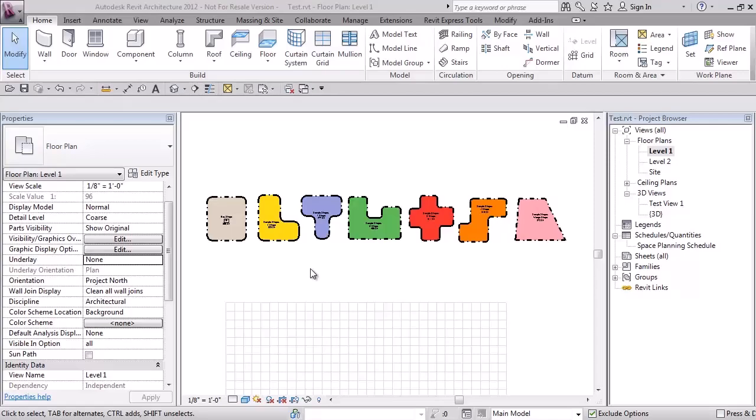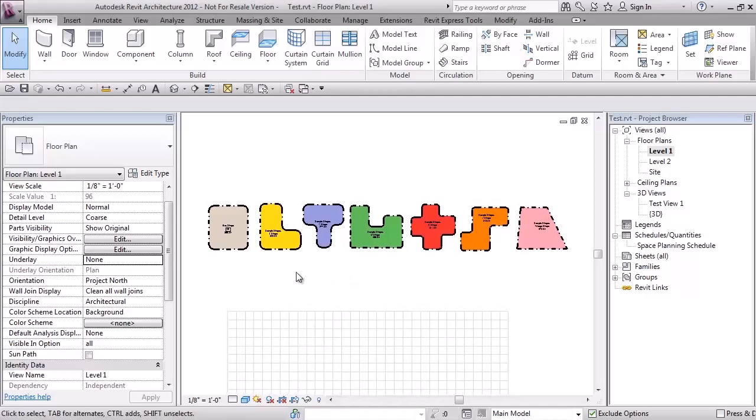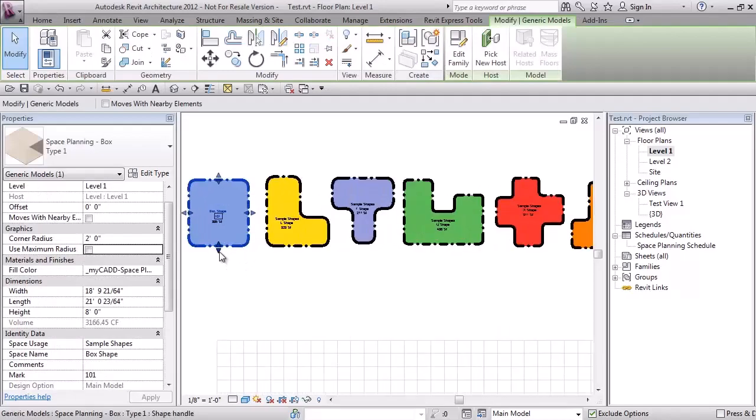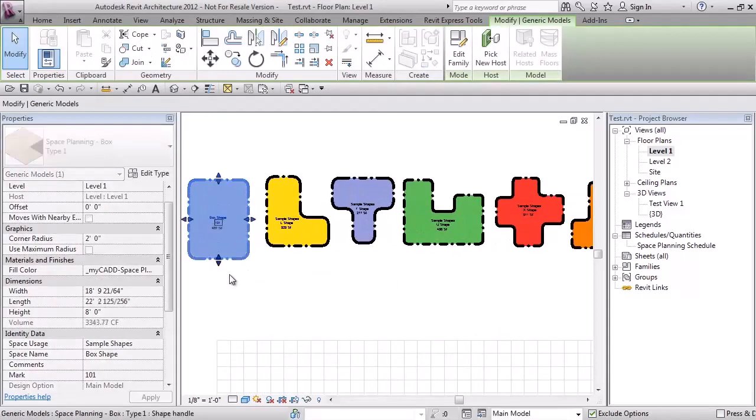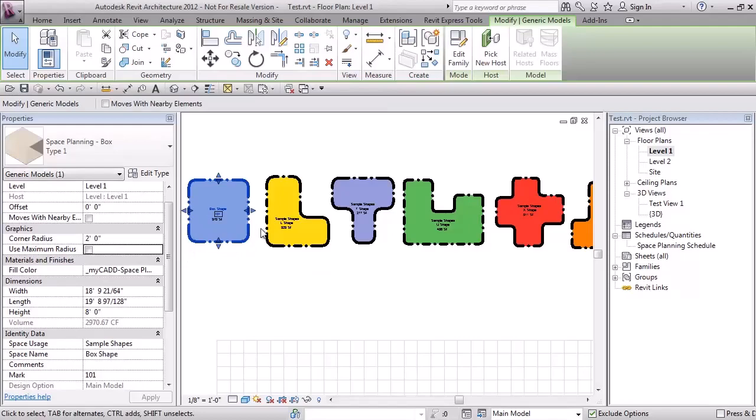We created these to fill a need in Revit for early design work. They're useful for space planning, adjacency studies, bubble diagrams, things of that sort that you do early on in the design that Revit doesn't really provide a good tool for. So there's a variety of families that you'll get in different shapes. Each one has easy to use stretch grips on all sides, so you can just select one, grab a grip, stretch it around.